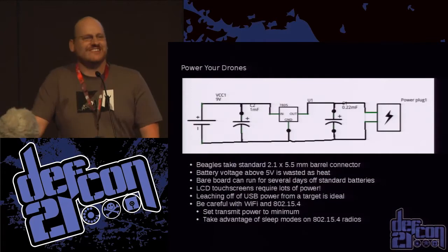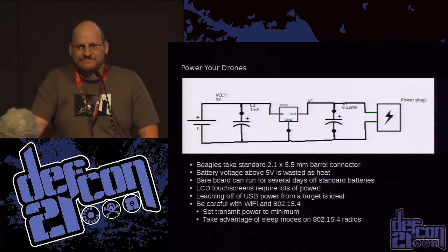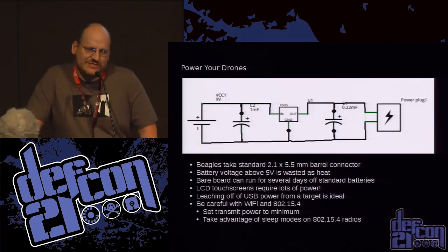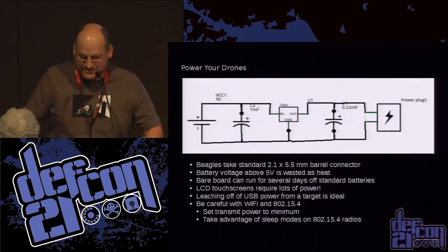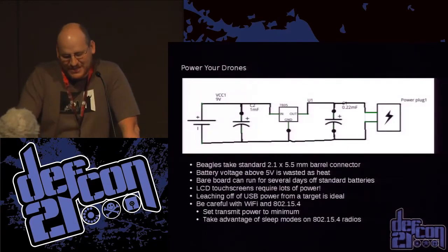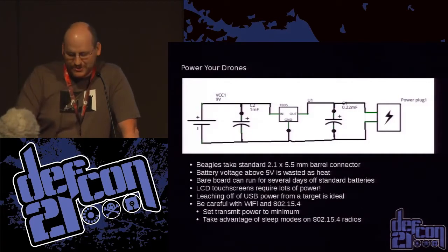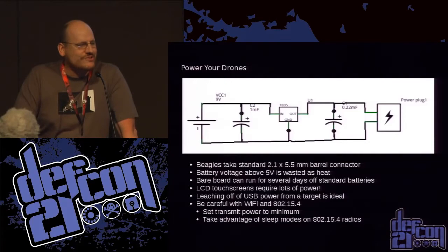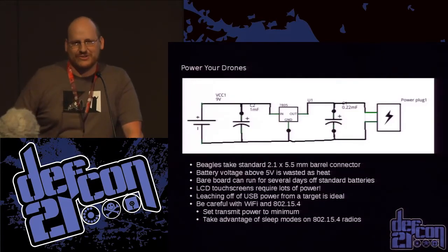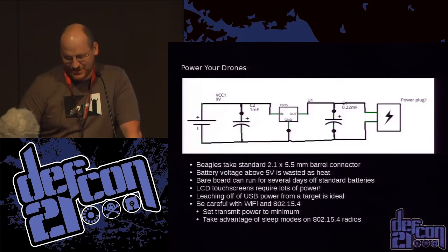It's over 2, and it does less. But it doesn't matter because all you can do is blink LEDs and they're pretty efficient, so it's all good. But one thing to keep in mind when you're using your mesh networks, the transmitters do use power, so don't just sit there and transmit constantly. Make use of things like sleep modes and such.